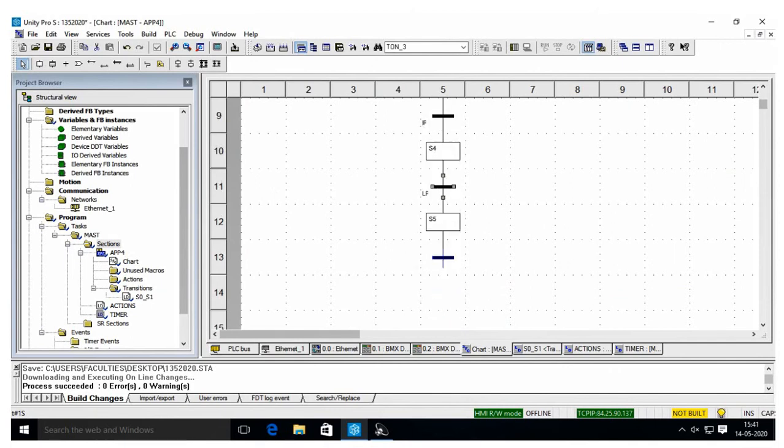Okay, so now I want to check for the condition. For that condition I have to draw the alternate branch. Here you can see, this is the new one, you might not have seen. So this is the alternate branch, so I will put the alternate branch here with 2 transition conditions. Okay, I told we want to complete the 2 cycles. As of now only 1 cycle is completed. 1 cycle is not completed.